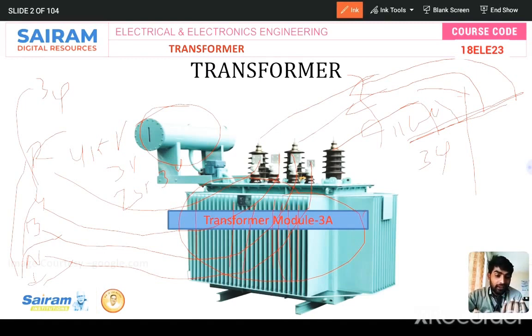If current is flowing through the conductor, heat gets produced, right? So it will be at the top. So again that recycling is for maintaining uniform cooling. So we have fins over here for cooling, and here there is a Buchholz relay for safety purpose.